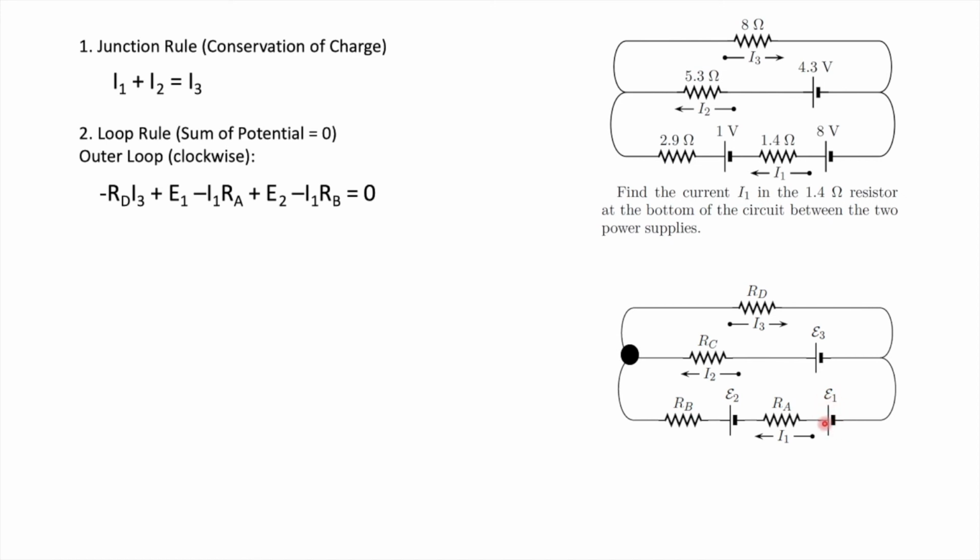So again, that's the voltage, right? And that's positive. And what's the potential or the voltage here for that charge? It's going from high towards low, hence the potential decreases, right? And that's I1 times RA1, which is negative.